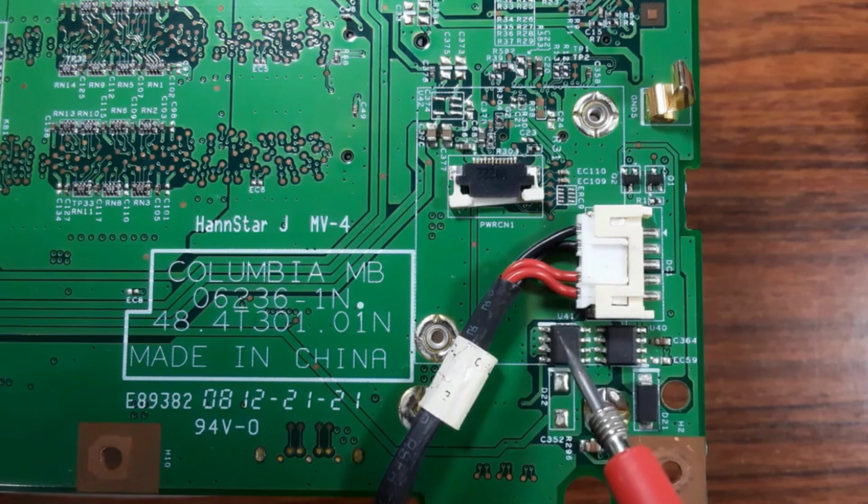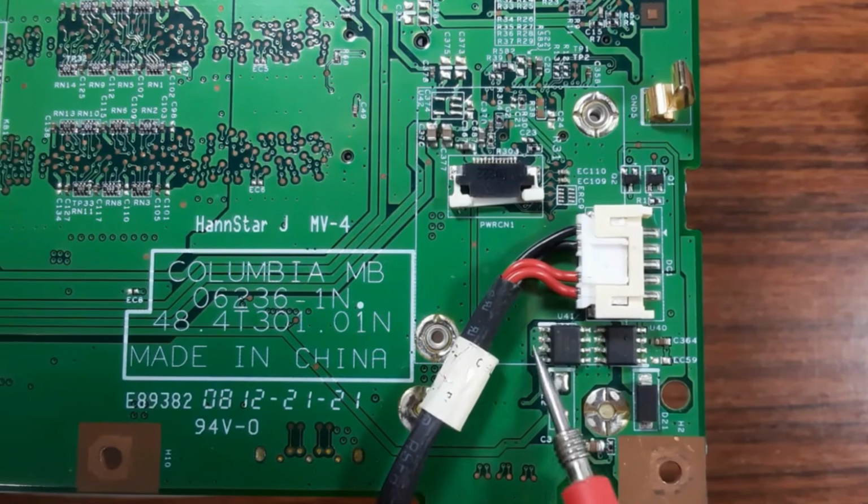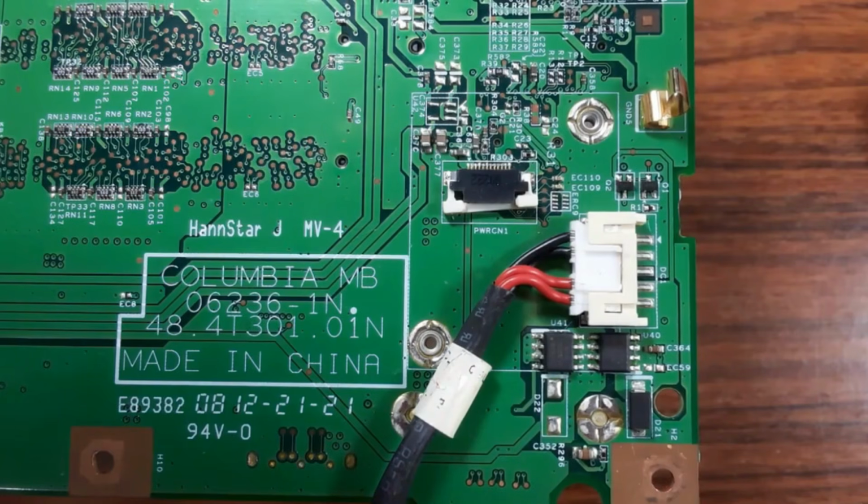Of course, here we have this point, this dot, and this mark. This means this is the pin number 1, 2, 3. These 3 are source. This is the gate, the control signal. Here we have the drain. So this point here means this source is connected to other components in the other side of this motherboard. When you find this dot like this, it means this source is connected to 4 components in the other side of the motherboard.